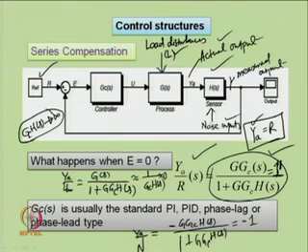But one thing one has to make out, if you look carefully, the noise is not getting suppressed, y A is becoming minus n. So, the noise is not getting suppressed with the high gain of the controller.